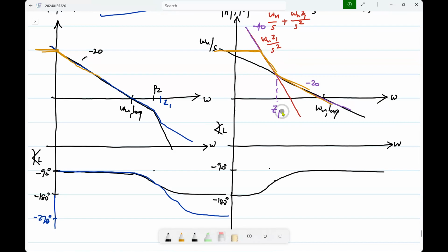So that is one reason why you don't, whereas the Miller compensated op-amp, it's easy to use it as a general purpose op-amp, the kind of op-amps that you buy in the lab. If you use it for any gain, more than one, I mean, gain usually means 1 or higher, you will be fine, as long as they have ensured that it is unity gain compensated. In fact, if you have seen the data sheet, it also says unity gain compensated. Whereas the second one cannot be used like that.